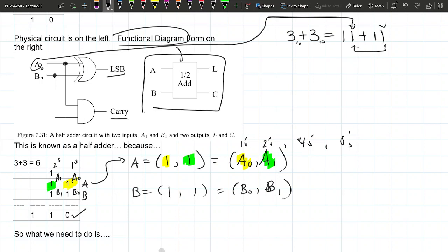A0, B0 also go into the AND gate, which is what's going to connect to the carry. There's a lot of arrows going around, unfortunately. And that indeed does give me 1. If I have some magical power that allows me to use the same half adder once again, A1 can be reused. Instead of using the 0, I'm just going to go to 1. The XOR between 1, 1 should be 0, but we want a 1 there.